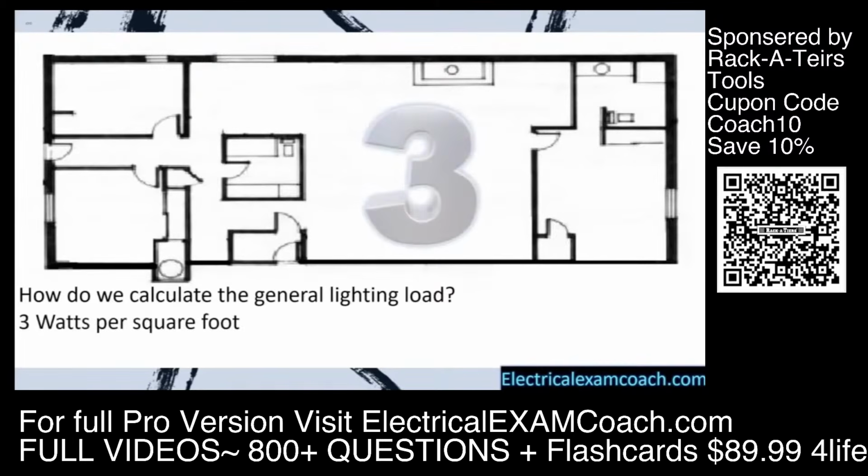So we're going to calculate it at 3 watts per square foot. So for all of the general lighting and all of the general receptacles, all we have to do is take the square footage of the dwelling unit and multiply it by 3. But the code language actually uses VAs. So 3 watts per square foot or 3 VAs per square foot.